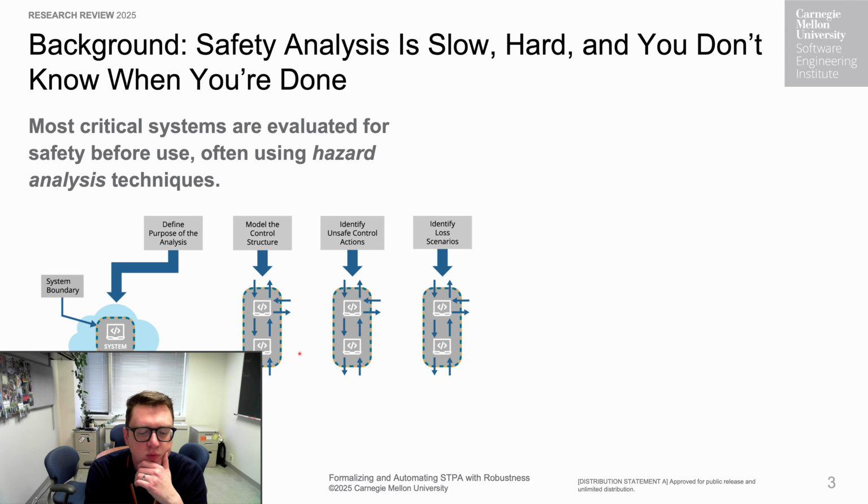And by that I mean, if our airplane controller needs, say, the airplane's speed, it's not so much that something is sending speed information back up as it is that the controller is reading some sensors and then deriving from that some speed information. But it's helpful to think in an abstraction where we have higher level components, which we term controllers, sending control actions down the abstraction hierarchy to lower level components, who themselves might be controllers for even lower level components. But then they send feedback back up. And that lets the controller estimate the state of the world, the state of the controlled process, and make decisions based on that.